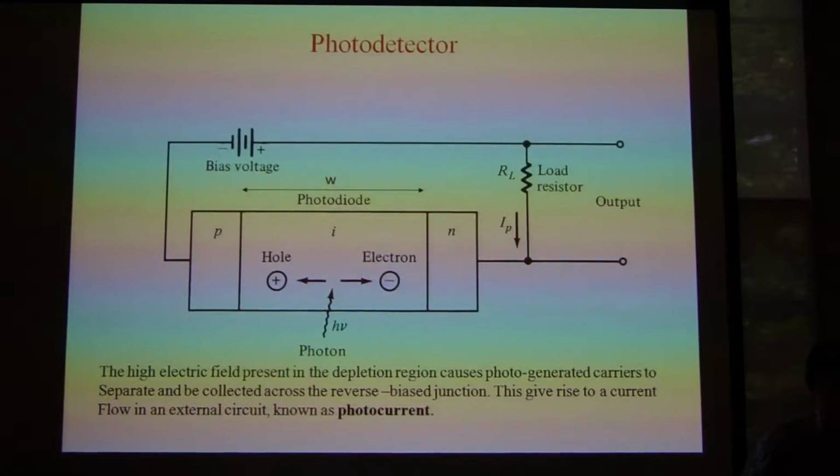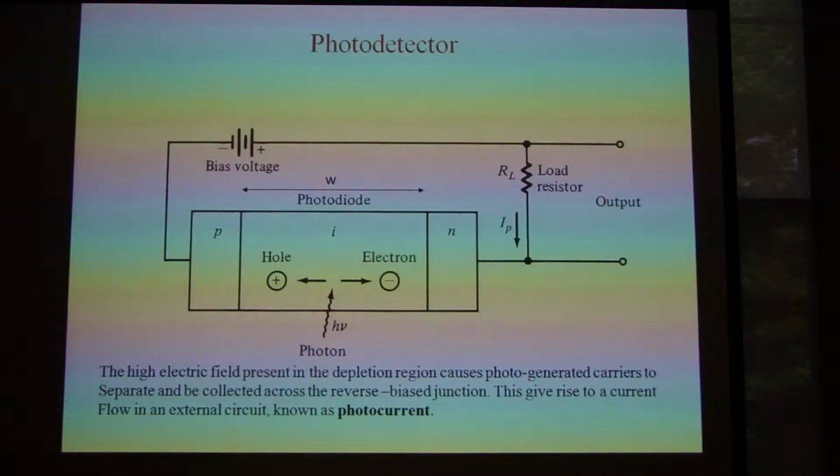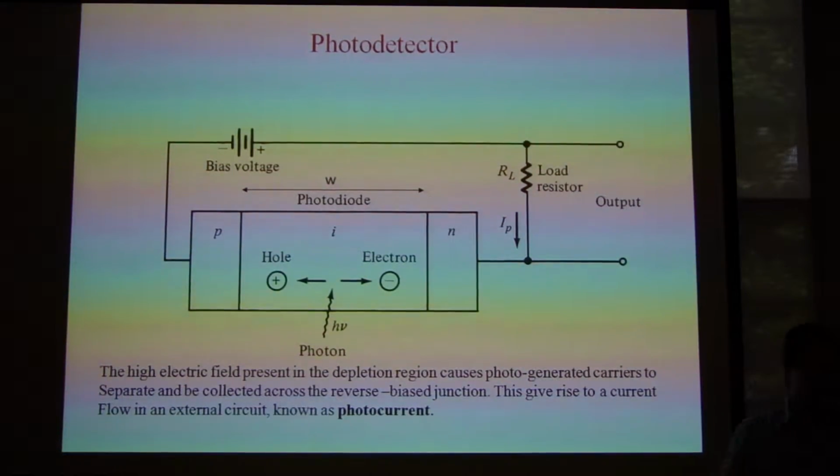Well, think about LED: it's something where you need to generate photons out of electrons and holes. So you need to inject. In order to inject, it has to be forward biased, right? You need the current to start to flow in the circuit.